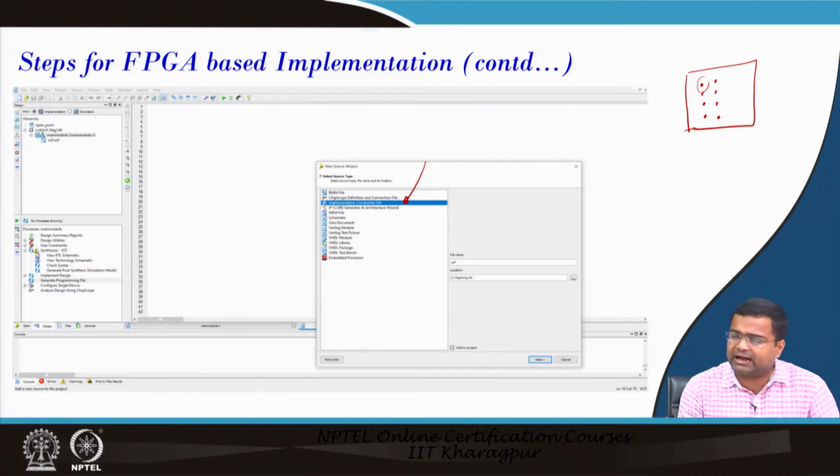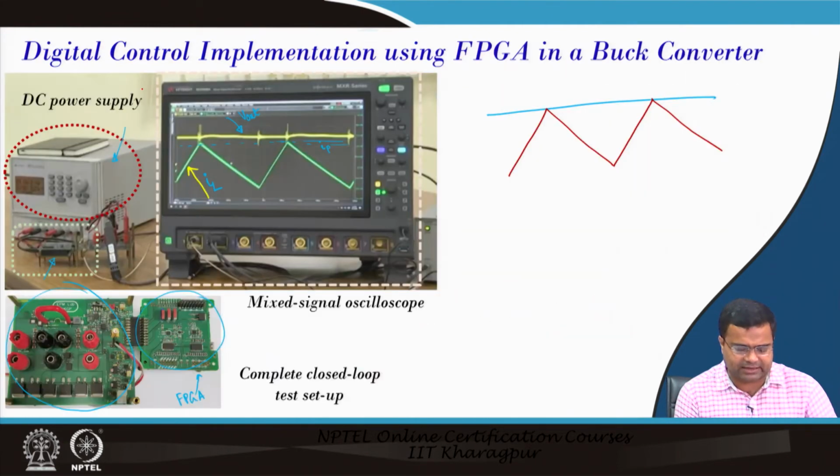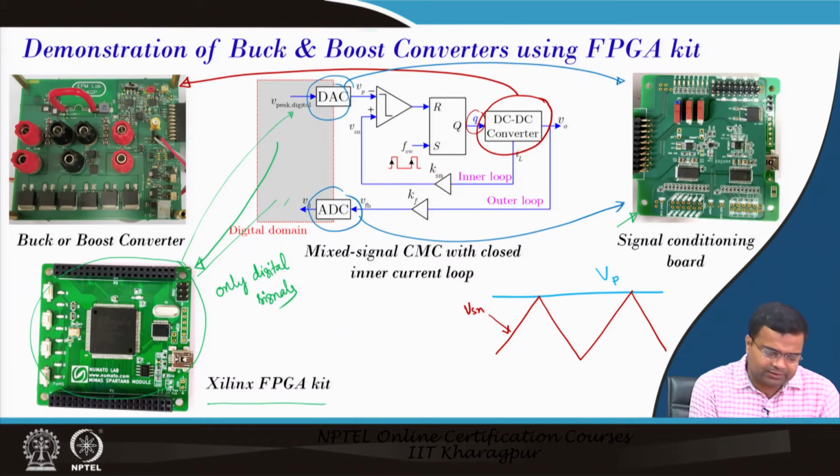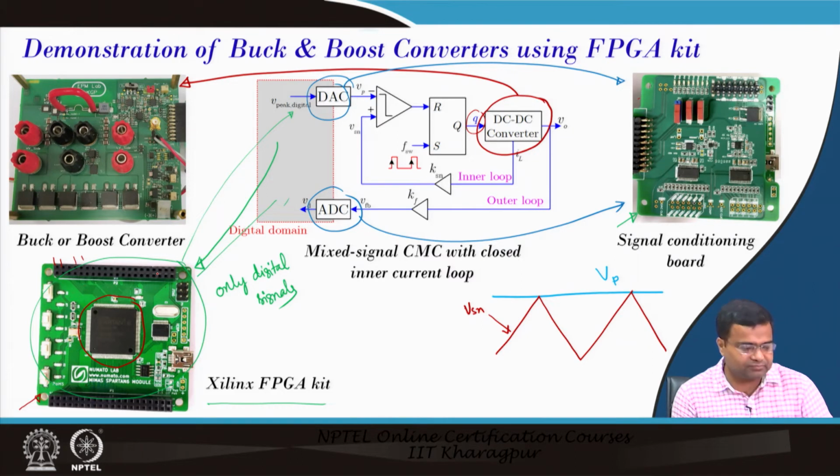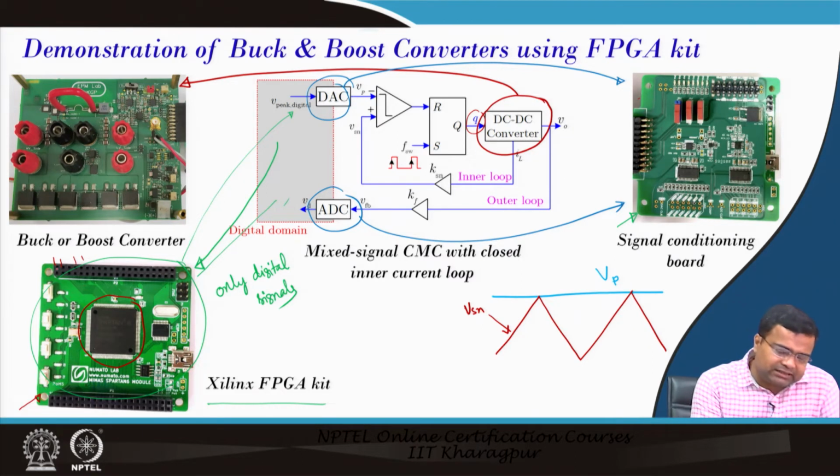they make sure of it. If you look at the FPGA kit that we are showing here, this FPGA is made by Xilinx, but this whole kit is made by Nomato Lab in association with Xilinx. So you need to know the address of this pin, not the FPGA pin, and what address you have to define. But eventually some of these pins will be connected to the FPGA pin.